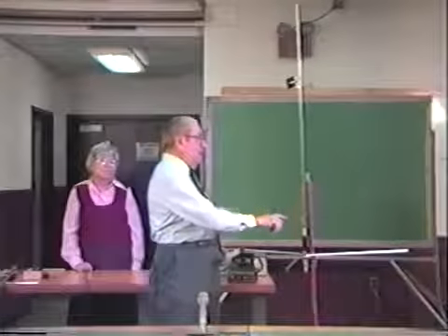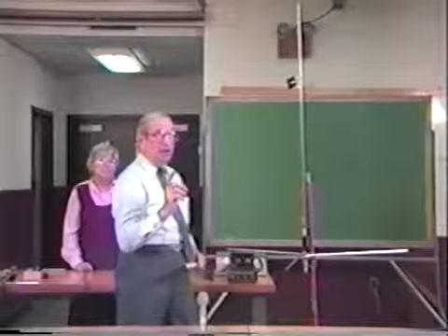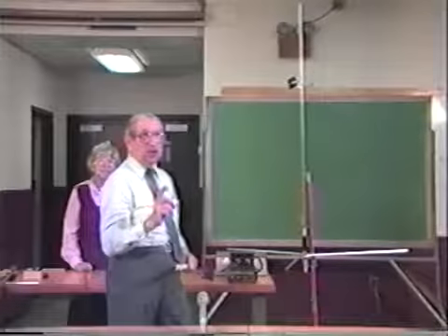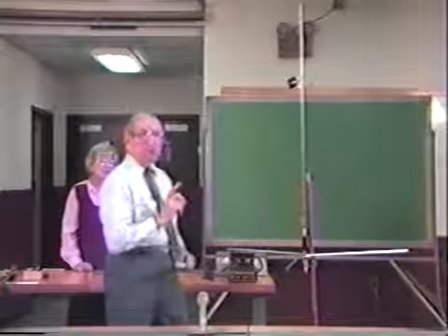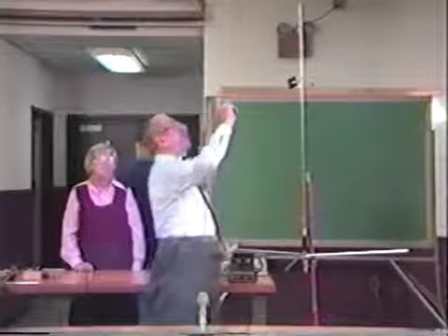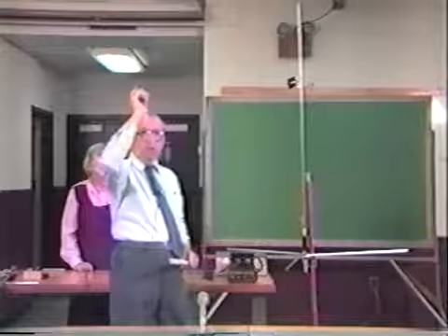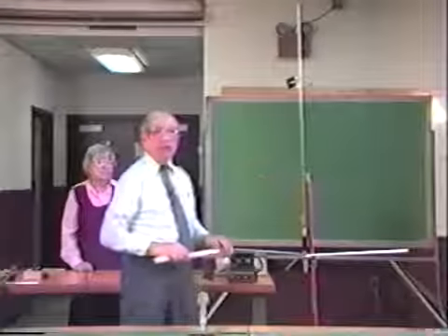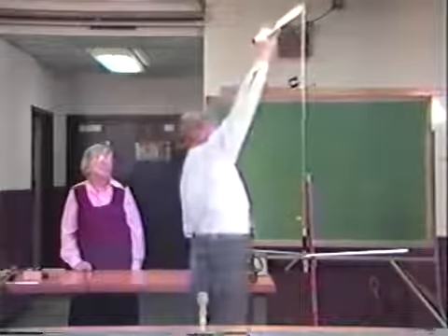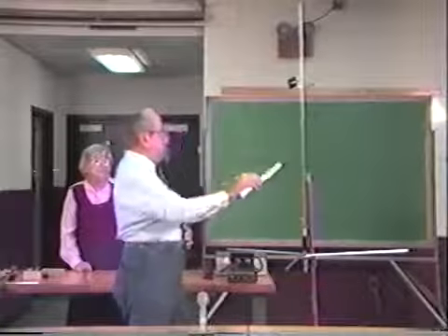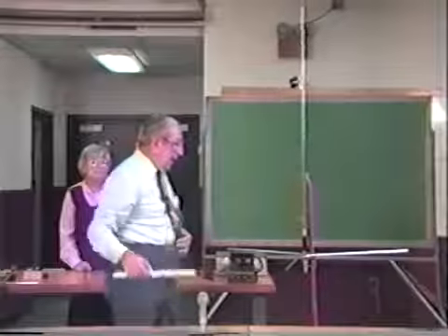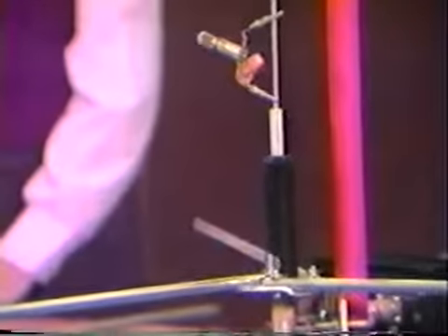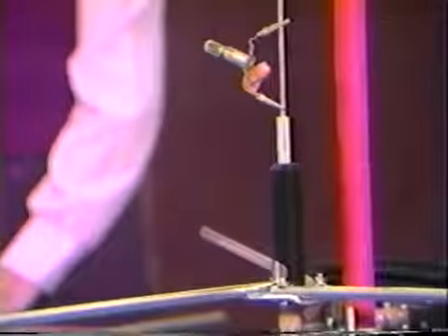So now we have an antenna. I told you it's electrically 3/4 of a wavelength long. Being 3/4 of a wavelength long, I told you originally that the end of the antenna is a voltage loop. If the end is a voltage loop, then a half wave down from the end, we have another voltage loop. So if I put the lamp up here, okay, can you see the light lit? Now, if I bring the lamp down here, to this point here, you notice I also have another voltage loop. I will not have the voltage loop down here, shouldn't be anyway, because this is the current loop.